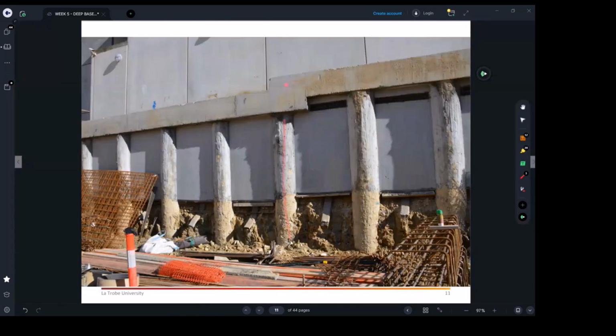So this is again the pile, which we built at the very start. There is also a pile cap on top, which we will talk about, and there is the shotcrete wall. Now, those 3 forms I was talking to you about: number 1, soldier pile systems, contiguous, and the last one, secant. It really depends on how far these are from each other. So that's basically the difference.